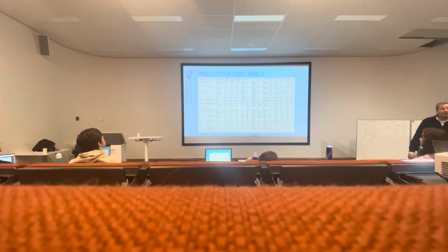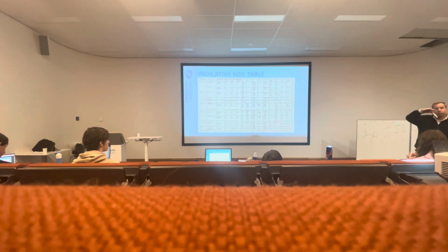Is it absolutely the case? No. Also keep in mind with these values, we don't take into account, for example, earthquakes, etc. What I mean with that is, for example, in Mexico, you have to calculate 2.8 times the weight. Because when you get a movement, you actually get 2.8 times that weight pushing on something. That's depending on every country.